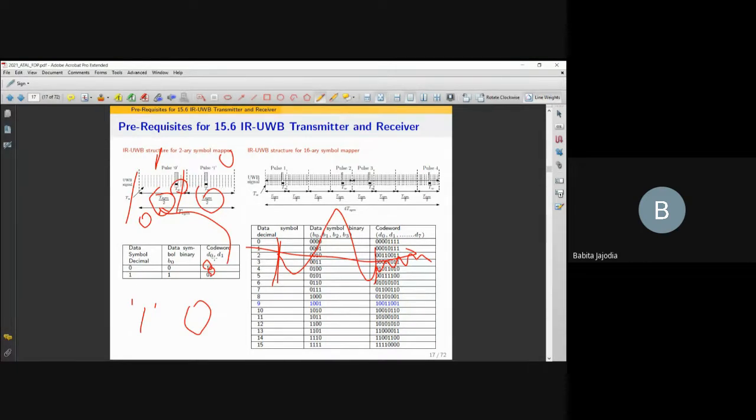So whenever it is required to be transmitted, we will be transmitting one pulse, even if it's 0 or 1, right? So that it will be clear: there is a pulse, that means the information has been transmitted. We could have used on-off keying as well, where instead of making a code word, we could say 0, there is no pulse, and 1, there is a pulse. But during the transmission, the noise might put a threshold because we will be using energy detection at the receiver. So noise might create such energy that might convert the 0 bit to a 1 bit.